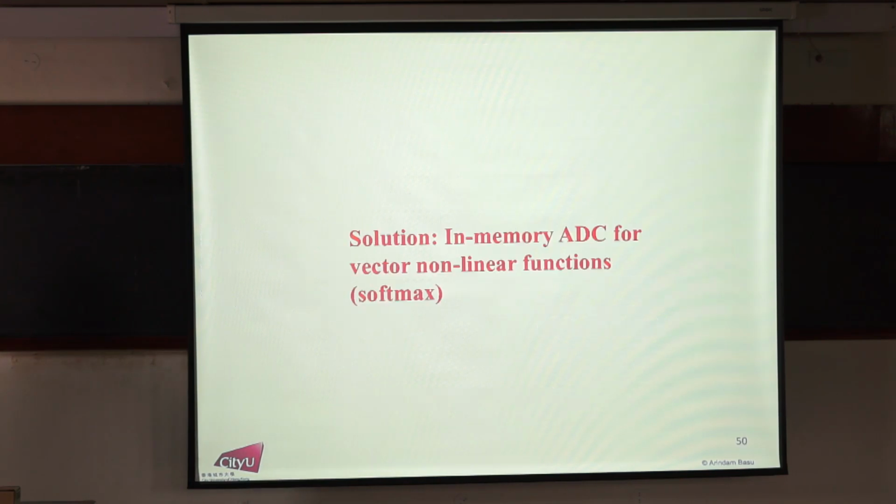Same task. These SRAMs are assumed to be far away from the computing unit, right? They're not like distributed near memory. No, these are in-memory computing SRAMs, whether it is next to the compute unit which is doing the inner product. The memory is doing the inner product. So this is in-memory SRAM. I didn't show you any near-memory stuff yet.